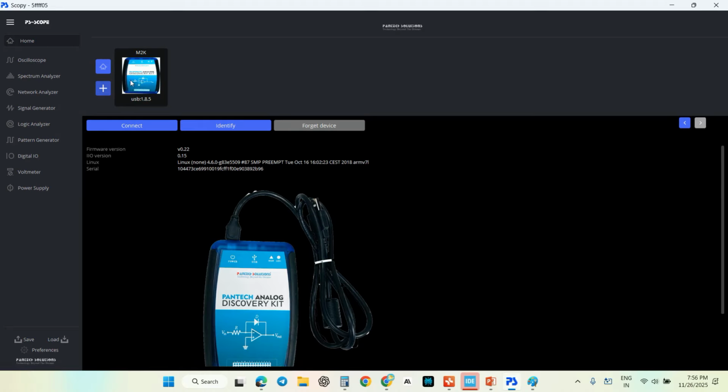So how I made the connection is only two connections, guys. Here you can see the pinouts at the bottom, so you can connect to the pins. One pin is connected to port B9, because the timer is going to be configured with that GPIO pin. Another one is grounded. Just simply connect it. This is how it looks, connected to my microcontroller, which is going to be creating some blocks.